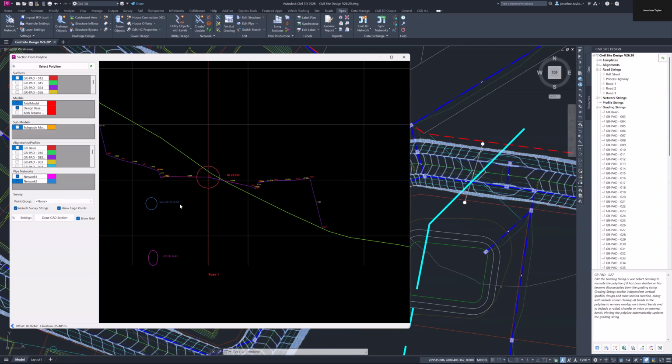that is another kind of handy tool, really, because normally trying to determine level difference, even visually, you're looking at the model viewer using the inquiry tool, which we spoke about earlier, to determine level differences. Just having a quick visual guide as to where your pipes sit in relation to each other and those center RLs can be a quick way of being able to determine where your pipes are in relationship to each other.